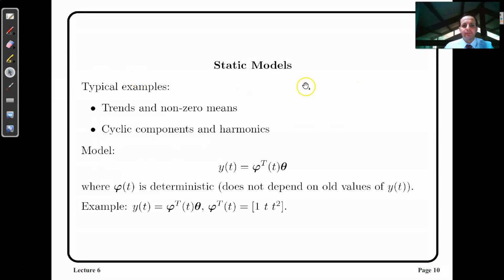So we say that the first approach was with static models. A static model means you are considering what we call a finite impulse response model, FIR. FIR is a very simple model, which means that the output is simply a moving average.